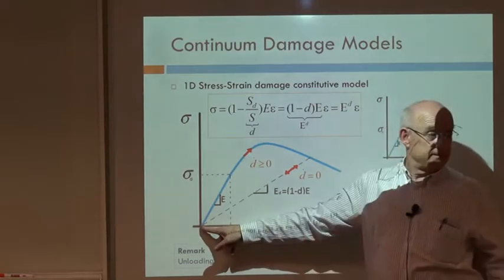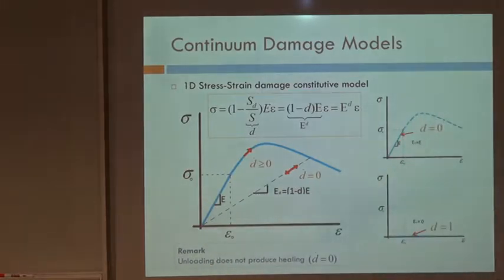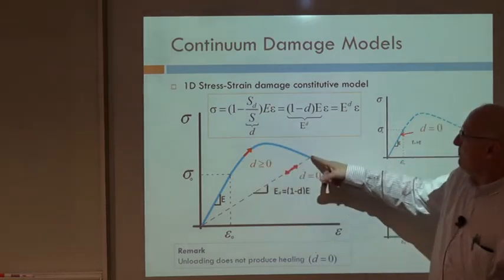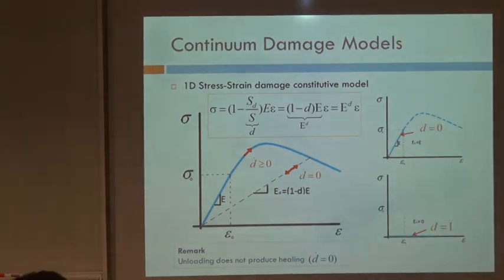So there is no permanent deformation? No, there is no, as you say, there is no permanent deformation in this, that is specific of these damage models, in contrast with the ones that we'll see later, which are the elastoplastic models. Okay? So that's why, for instance, for metals, this doesn't work, because metals are characterized by that. But what are called quasi-brittle materials, they are like that. Materials that break very soon. They follow this way, at a certain point they break and they go back to zero stresses. Okay?